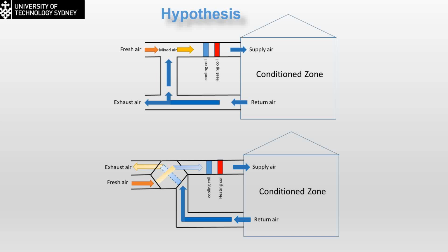So did you run into challenges with numerical model convergence? Yes, I did a sensitivity study. I didn't show it in the thesis, but I refined the mesh by a certain amount each time until I got this value, 2.5 million. So you did some sort of convergence study to make sure that 2.5 million is adequate. Yes, otherwise it's not going to be acceptable. But once again, I didn't include this study within the thesis because I tried to make it shorter. Let's put it in the appendix.